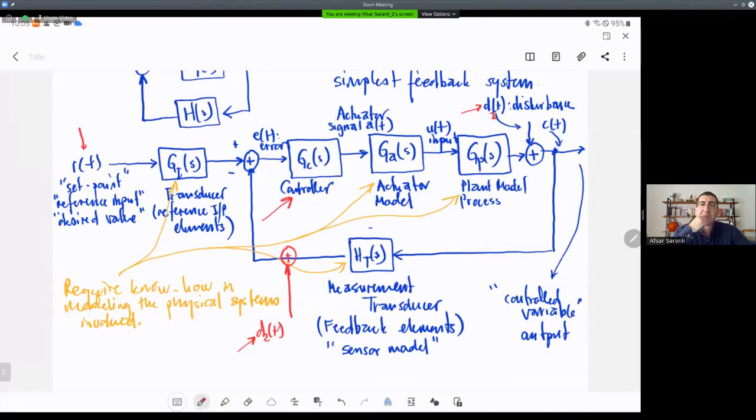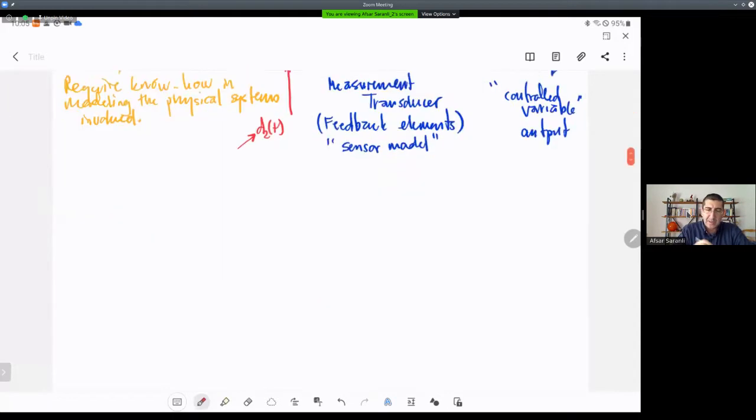The presence of a linear system with the superposition principle allows me to combine the individual output responses to each one of the inputs at the output, okay? So in terms of circuit theory terminology, you kill a particular source, or you kill all sources except one, and you can calculate one by one the contributions to the output, okay? So let me write this down.